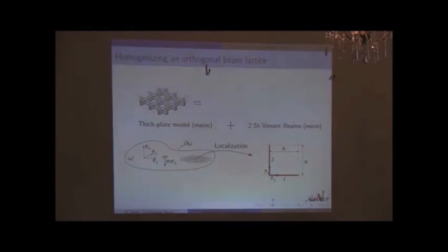So, I rephrase this. This is the Reissner bending constitutive equation. This is a 2x2 matrix. Since I have orthotropic symmetry, meaning I have two vertical planes of symmetry, and the pattern is invariant by a rotation of 90 degrees, this tensor must be isotropic, meaning I have some constant times the identity.